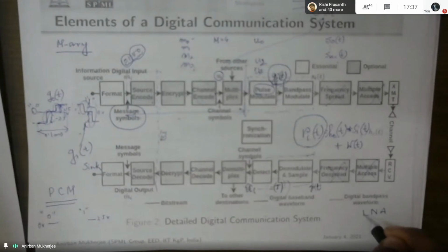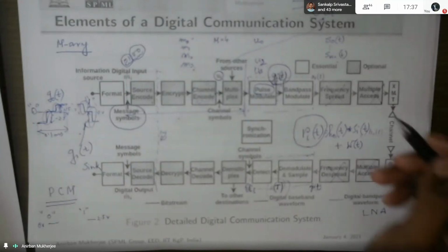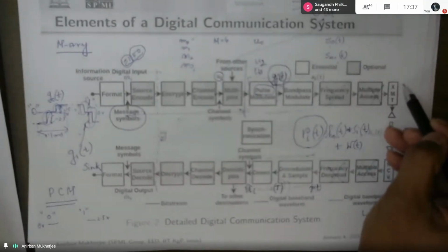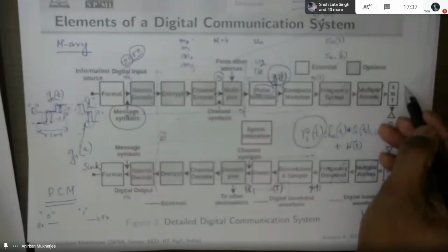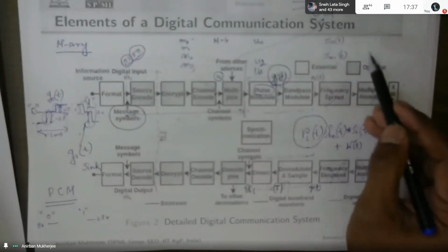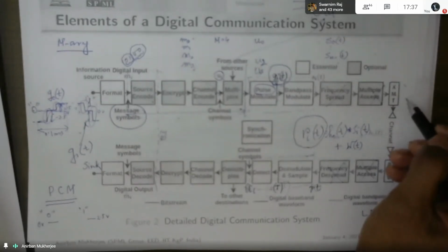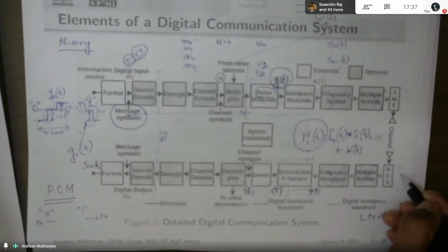Now this received signal goes to the receiver front end, which works in the reverse direction. The receiver front end and demodulator provide the down conversion for each bandpass waveform. Generally you have a bandpass waveform. Here I told you about frequency up conversion: s0(t) is at a megahertz level, and you generate it at a 2.4 gigahertz level. You do this frequency translation for each s0 to s(m-1), and you have it received over here.